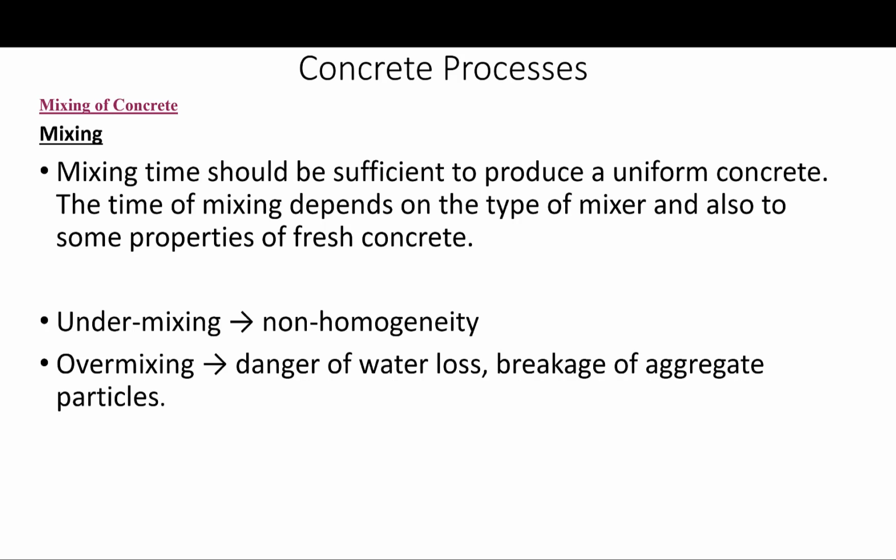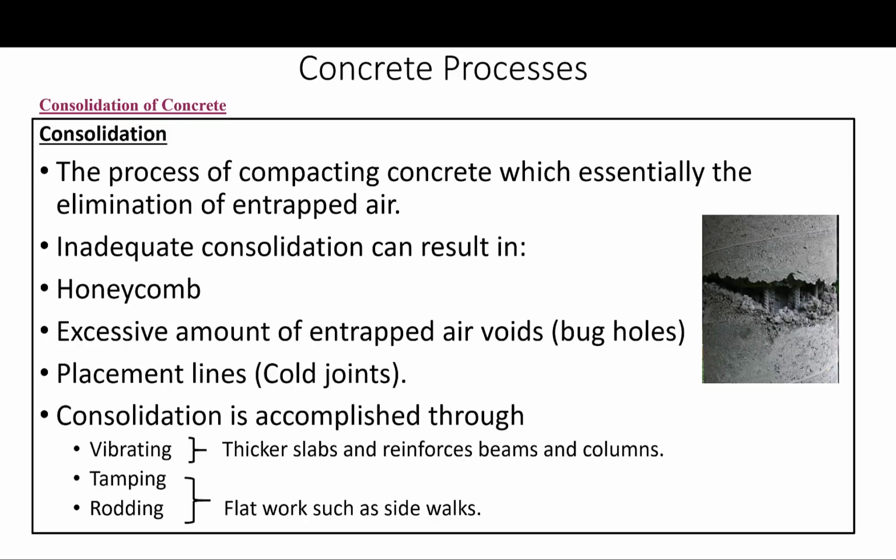So we want to avoid undermixing, which will produce non-homogeneous concrete, or we want to avoid overmixing, which runs the danger of water loss or breakage of aggregate particles, for example. So something that has to be basically looked at. The second process is the consolidation.